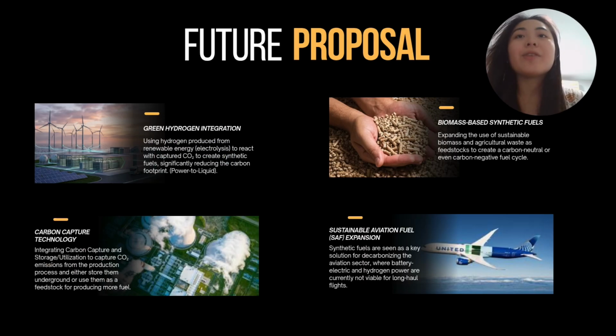Looking ahead, the future of synthetic fuels is actually very promising, thanks to several emerging innovations. The most exciting development is green hydrogen integration. Instead of using fossil fuels to produce syngas, we can use renewable electricity to split water into hydrogen and then react it with captured carbon dioxide to create synthetic fuels. This is the power to liquid concept.